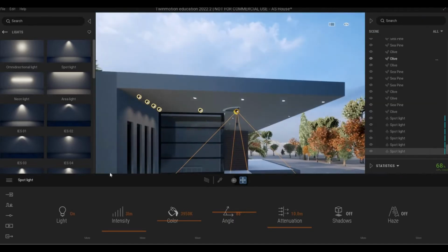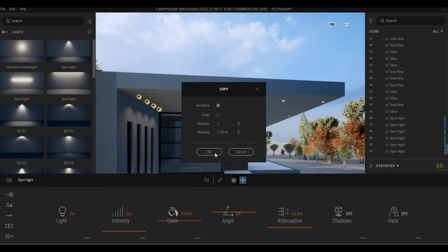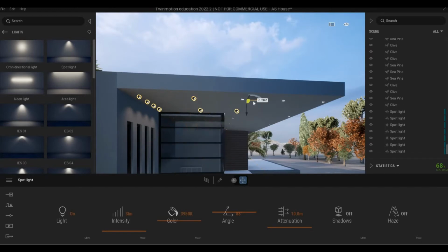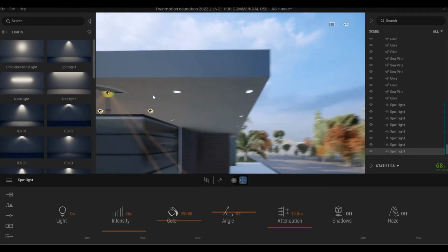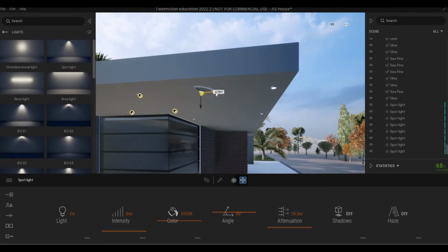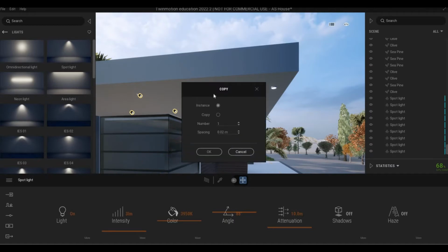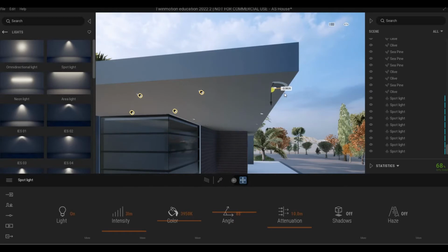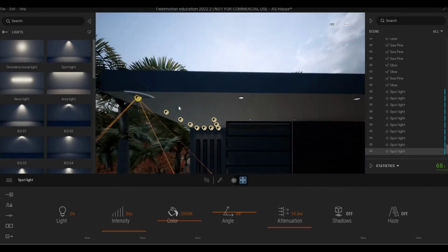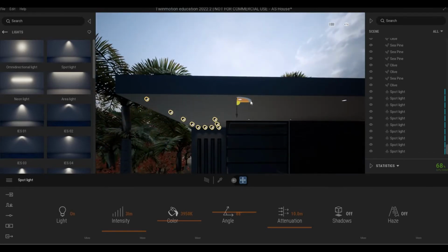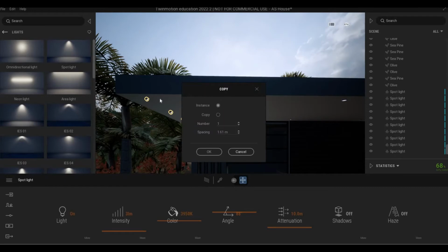And then this one can help because if you click this, it will be in the same line as well. And then the good thing about copying as an instance is if you change one, it will change on all. Oops, cancel this. Hold on shift and grab it from the corner here. And then now we just need to keep on adding it. Oh, sorry. So cancel this.